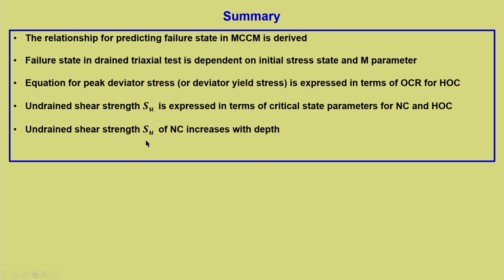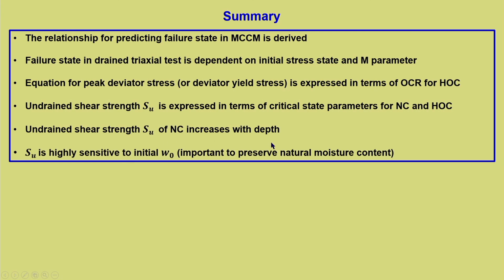Undrained shear strength Su of NC increases with depth, that we have shown. Su is highly sensitive to initial water content. So, it is important to preserve natural moisture content. That is all for today's lecture.